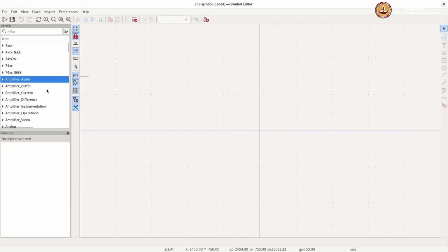So if you click on this arrow button here, you will see all the different components in the library. But remember, most of the symbols here have footprints, which means that they are more suitable for making the PCB. For simulation, the number of models are less, and then you will have to include the models on your own by taking it from the net or from the website of the company that makes the particular component.